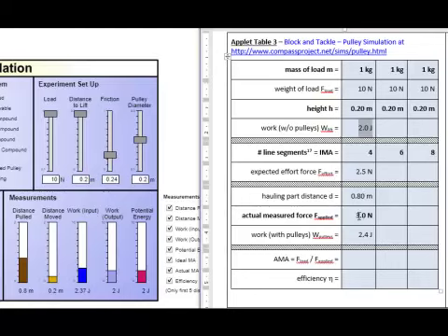In any case, the actual mechanical advantage is determined by dividing the 10 newtons, the load force, by the applied force. So 10 divided by 3.0 comes out to 3.33333. Technically two significant figures, but for the mechanical advantage, I really like to have integers, because you're not going to talk about a machine and say, hey, it has a mechanical advantage of 3.33. No, let's just call it 3. That's good enough.